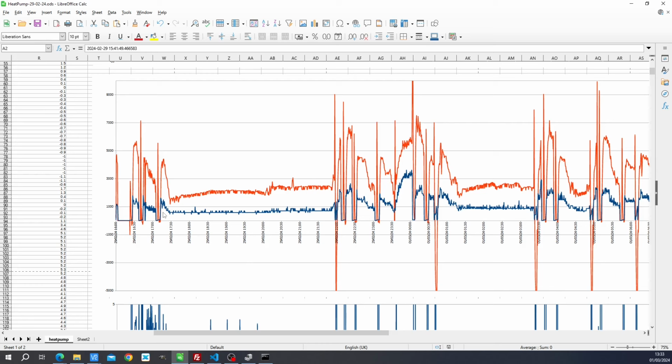Now, one of the things I've noticed is that there seems to be a minimum power consumption for the inverter. The lowest I've seen it over a long period of time is 2.3 amps of current. That's about 560 watts, I think. And that's interesting in the sense that it can't drop any further in terms of output. And when the weather's cold, like it is in this region, that's fine. It's in a happy zone.